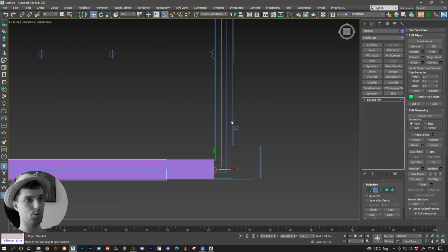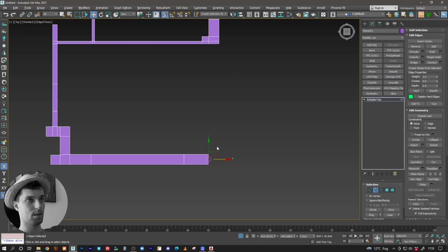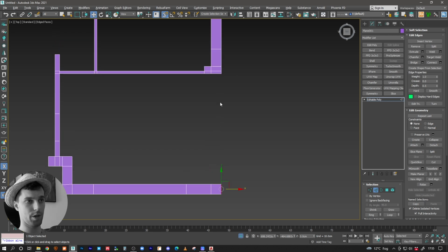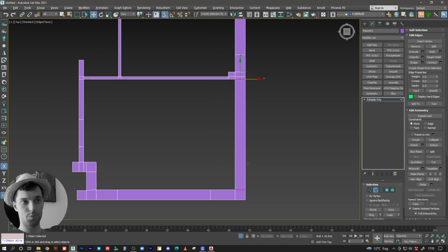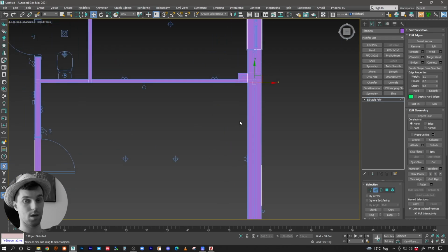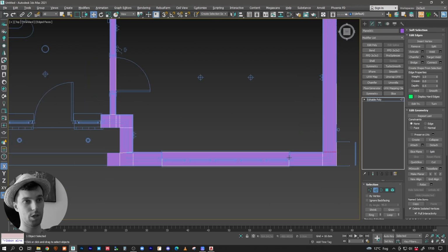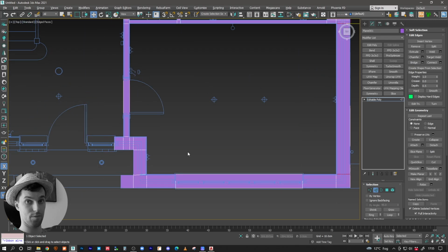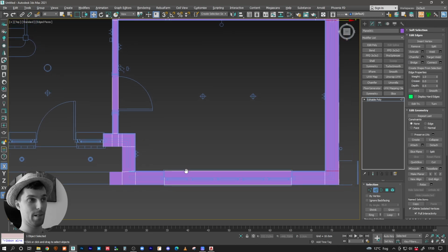The next thing I want to do is, I'm not going to snap anywhere here because it's a little bit imprecise, but to make it perfectly fine, just isolate the drawing, which is Alt Q, right? And I'm just going to shift drag it to there, select this edge and press bridge, bam. All right, this is perfectly straight. I know that it's straight because I didn't trace it with the spline, right? So I know that this edge and these vertices are completely straight to that edge, so I'm 100% sure about it, right?